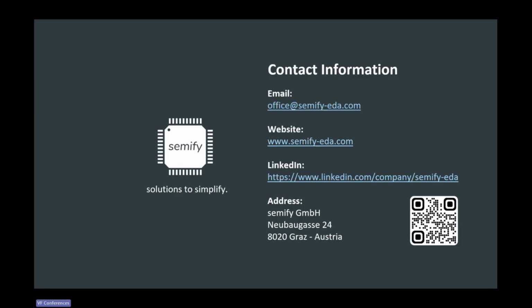Do you do this at the gate level with timing, or what level of abstraction do you run this? Yeah, that's a good question. Gate level is kind of a separate thing. You can catch basically all of these issues in gate level. The idea there, though, is that with gate level, you're still operating on the kind of naive modeling that I showed, where you have a setup and hold window. So again, it's not pessimistic enough. Gate level is also very slow compared to just doing this. So the idea here is you still run an RTL simulation. It's still very fast, still very lightweight, but you also do some CDC checks on top of that. And you make it more pessimistic than what a gate level simulation would be, with the hope of finding some hidden bugs.